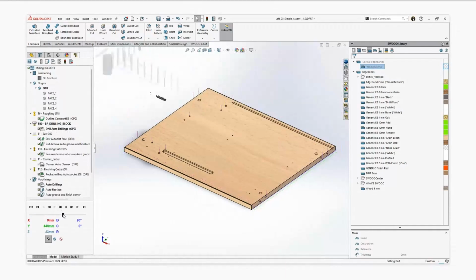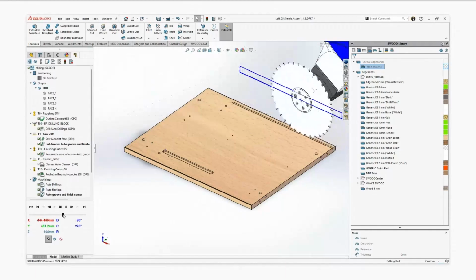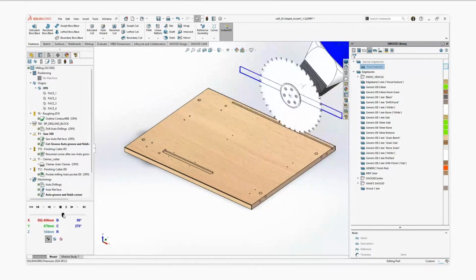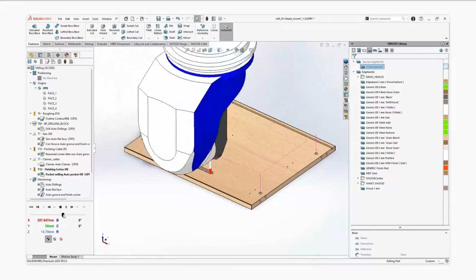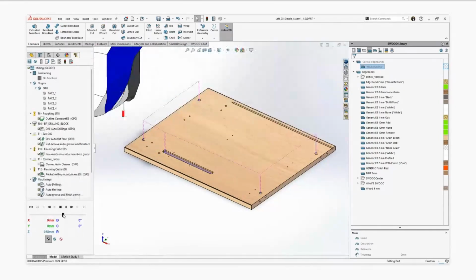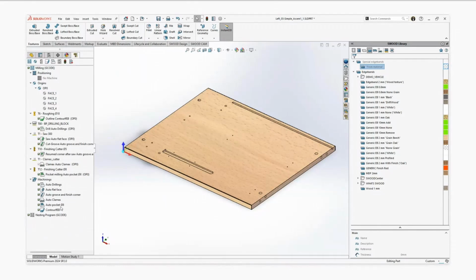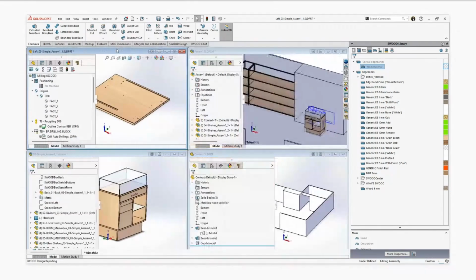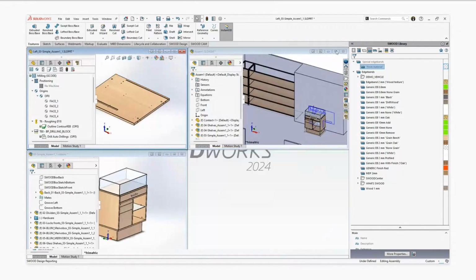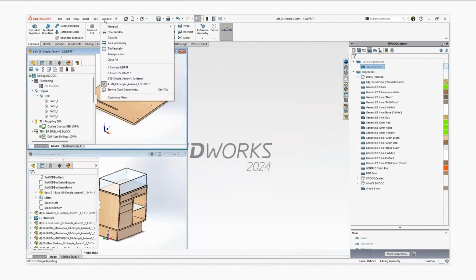Here, just the outline to avoid all the edge band, all the drillings, horizontal and vertical, all the grooves, and also an operation to just finish the groove, and all the pockets. Here, for example, I don't have a spindle for the horizontal hole. That's good, I use it as a pocket. And even if tomorrow I decide to modify, just to reduce this one and minimize.